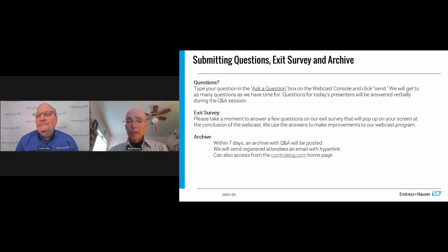Okay. Good. What protocol is used to communicate with the field devices here? Heartbeat itself is protocol independent. And one thing I forgot to mention when you asked me about the asset management is heartbeat verification itself is a DTM-based communication. So again, it's independent of the protocol. Typically you're going to do it point-to-point. If you are using an asset management system, we can drill down to the instrument using the DTMs, and we can use that to get to it as well.